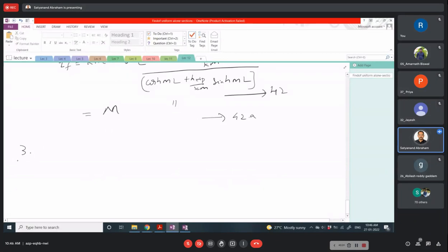Constant heat flux at the end is not that common; a more appropriate one is the convective heat flux. But more than that, what we have is an adiabatic tip condition. In case the tip is adiabatic and therefore not transferring heat, then we call it an adiabatic tip condition.